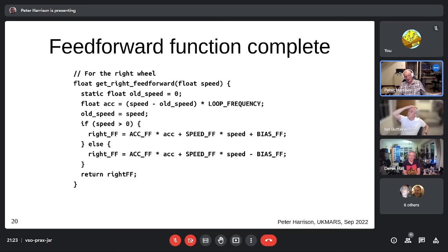So you could, I mean, if you wanted to you could put it on a drag race track, put 2 volts into it, right? And set up 2 timing gates a couple of meters down the drag race track and measure the time between the gates if you wanted to. That would be perfectly reasonable. Remember, it only took 800 milliseconds, 500 milliseconds to get up to its terminal velocity. If it was a very heavy robot and had a very low gear ratio, it might take longer. But the point is, all you need to know is that terminal velocity against voltage, and it doesn't matter how you do it.